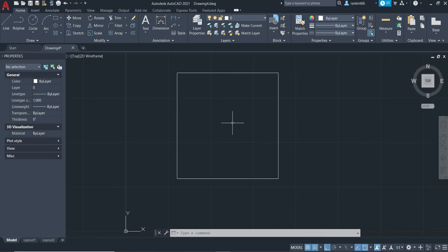What I want to do now is draw inwards so that I have my exterior walls. Instead of having to draw a box and place it in there, I'm going to use my offset tool. So I'm going to type in offset, and hit enter. The first thing it wants to know is the distance, how far inwardly I want this. For our exterior walls, we're going to give them 1 foot of thickness. So I'm going to type 1 foot, and hit enter.